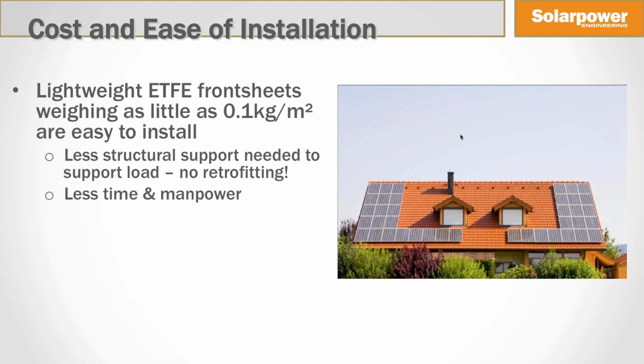For example, 75% of big box warehouse constructions in California are not suited for conventional solar installations due to structural limitations. In fact, most industrial properties built before the 1997 Uniform Building Code change are not suitable for conventional rooftop solar installations without costly structural improvement.